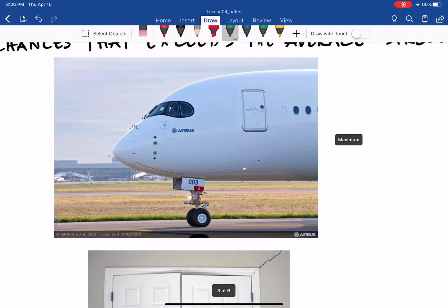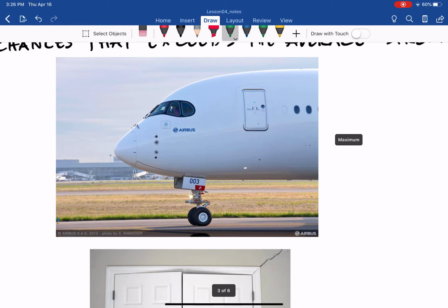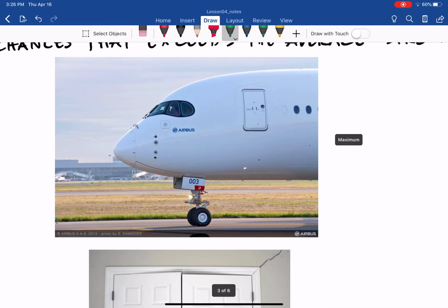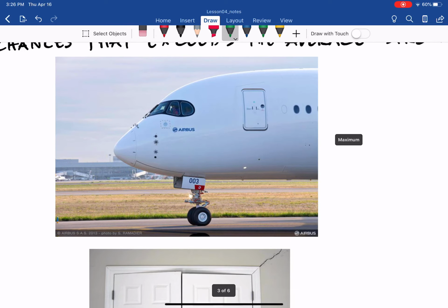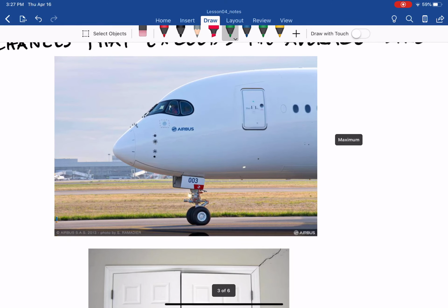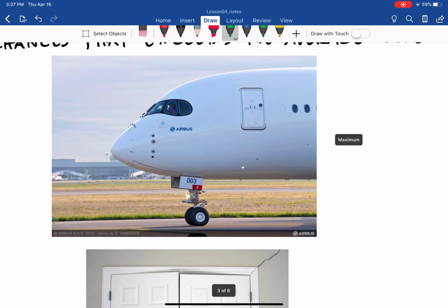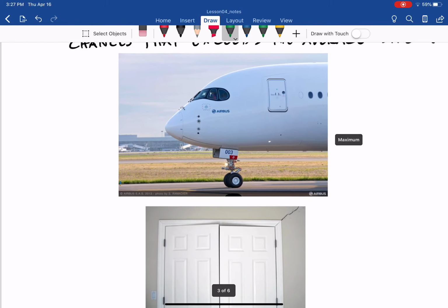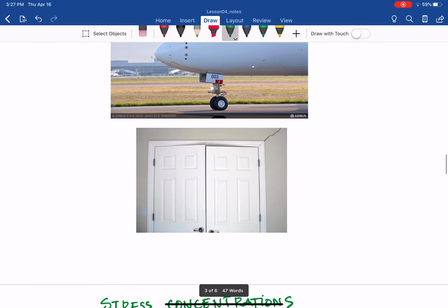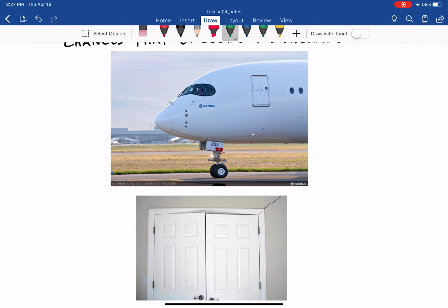The airplane, as you can see, takes off and lands, takes off and lands. One airplane can do this multiple times during the day, and that applies over and over, year after year, until the airplane retires. That is cyclic load. And with it, the stress concentration has to be considered even more, and that's why you see applications here that try to limit the number of discontinuities on the airplane body, make them small so there is less effect of the K, stress concentration, on a small hole, and add a reinforcement in that hole. That is the cyclic load.